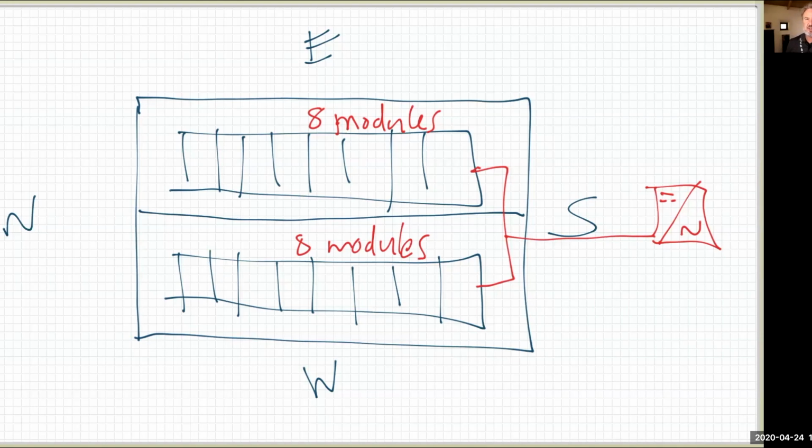Now, the question I often get as a follow-up on this one when I show this is, oh, yes, Glenn, sure, maybe it works. Sure, you're allowed to do it, but is it a good idea? Wouldn't you be better off using a dual MPPT? The answer is it depends. If there is no shading issues on either side of those roofs, actually the performance difference is very small, less than 1% benefit going for a dual MPPT. So there isn't actually a big performance reason to use dual MPPTs, but there is some caveats around this.